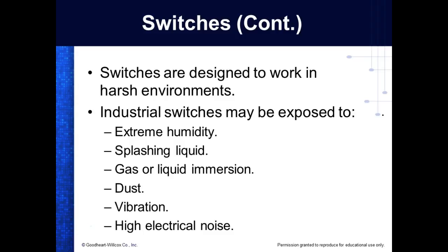So this is the limit switch. This is a high current, high capacity one. When we get into PLCs, guys, very little current is required by your input, so you'll run into these little tiny micro limit switches.